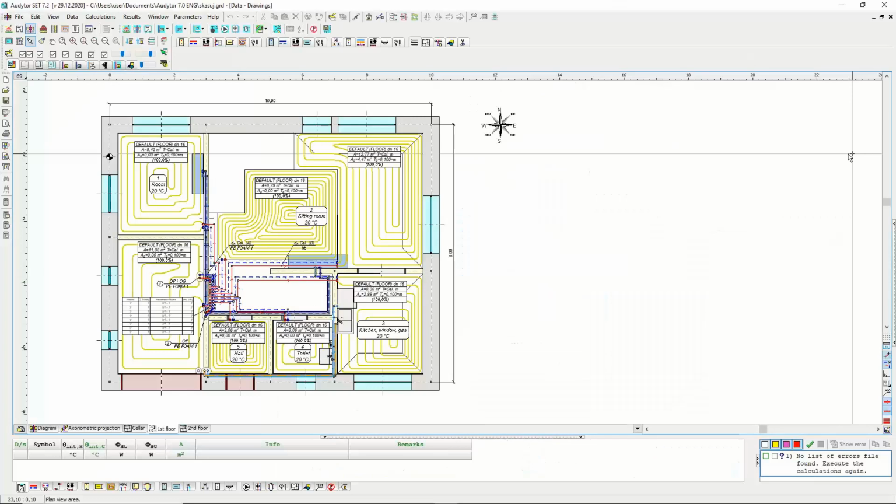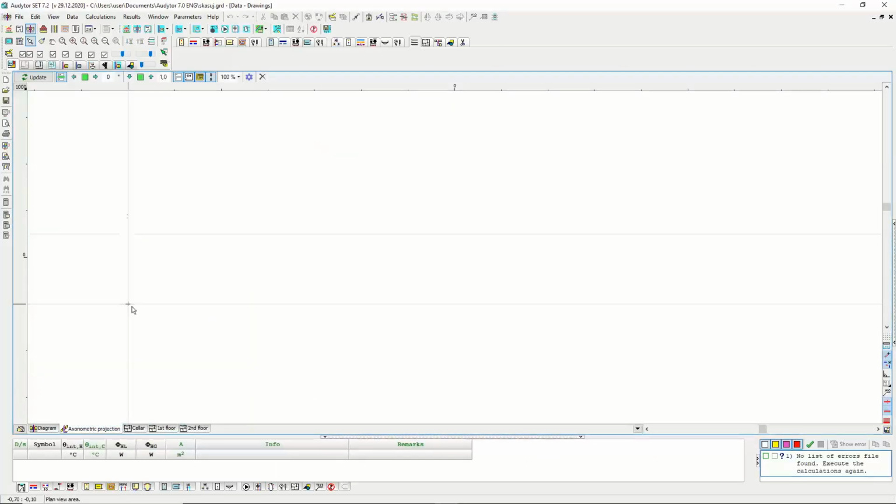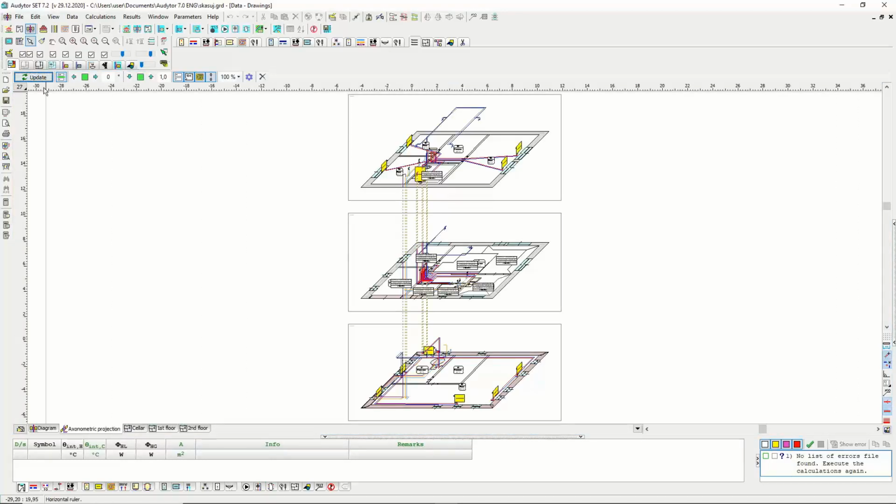If we can go to the software. So first, when I go to Axonometry projections, I can see just the white space. To obtain the axonometrical drawing, I have to click this button, update, and then I obtain this version that I already discussed, where the stories are separated.